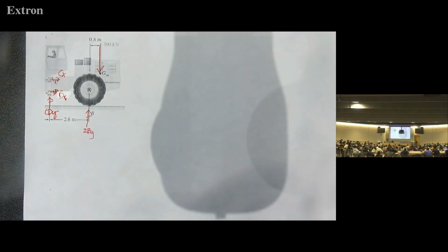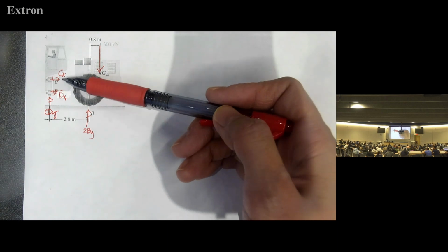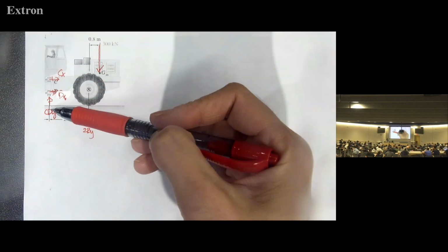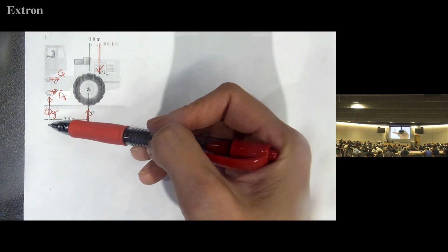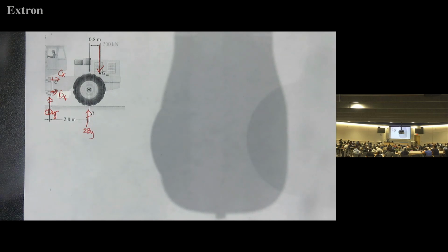So C and D could be the same magnitude in different direction or something like that, right? So that's a very good point. But for the free body diagram, we can define these two unknown forces in the horizontal direction because there are two connections, right? And then for the vertical, we need to define only one because one member, okay? Then now we are ready to solve the equilibrium equations. Any questions? So defining this is the most important thing here, okay?